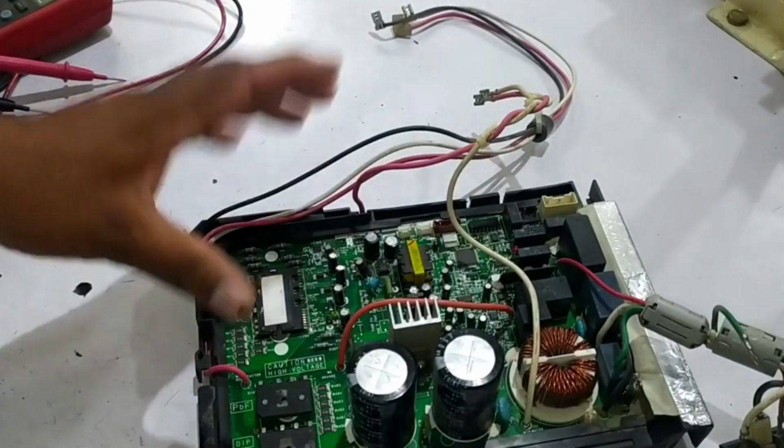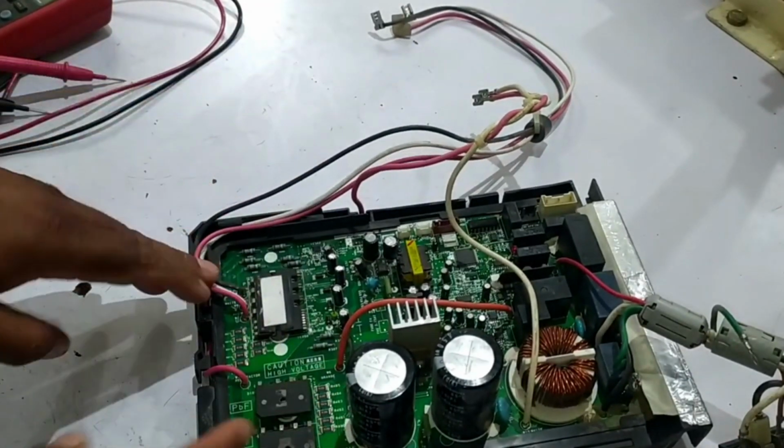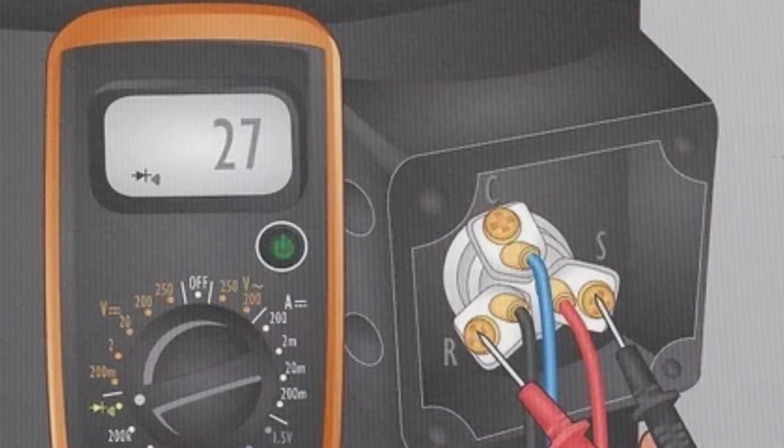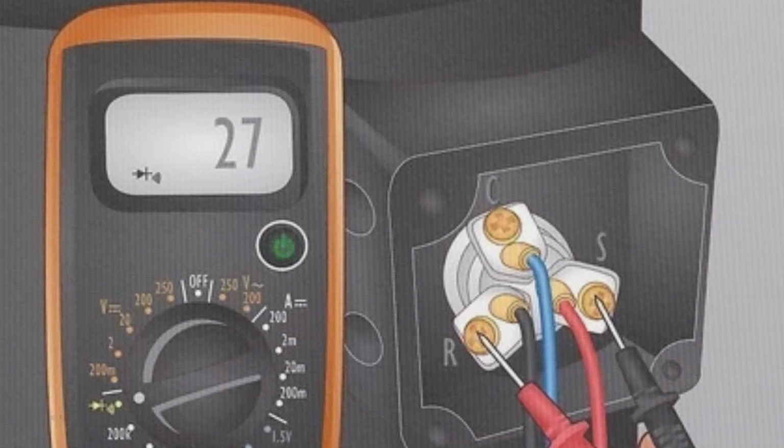Although compressors do not fail quickly, if all components have been tested and the error still persists, you should check the compressor's resistance to ensure there are no leakages. By following this troubleshooting process and checking all these components, you will be able to determine where the fault is and what caused it. Once the necessary repairs are made, the unit should function properly again.